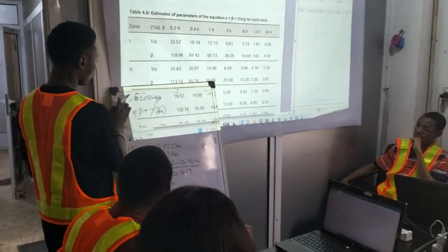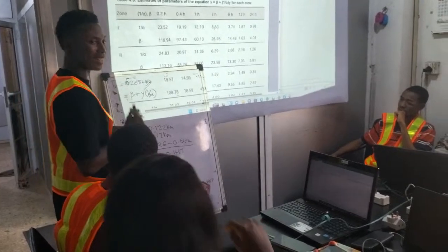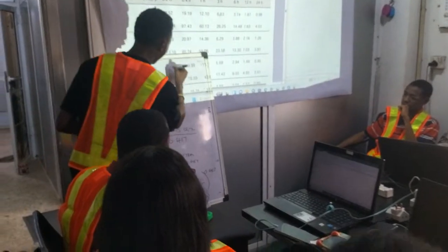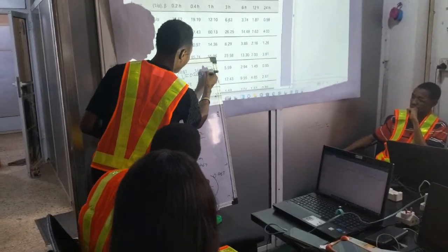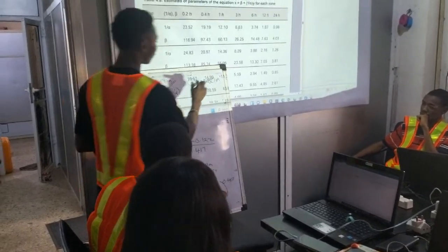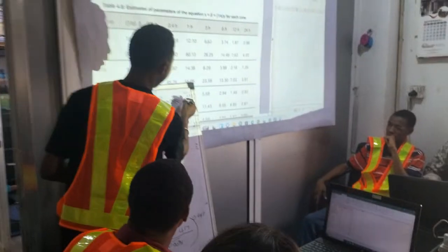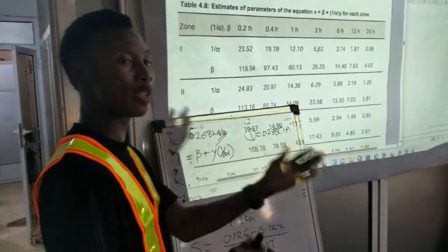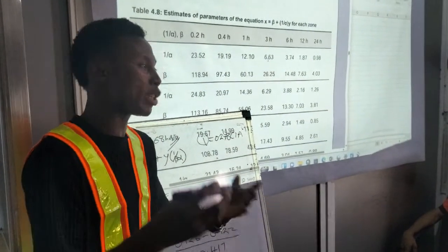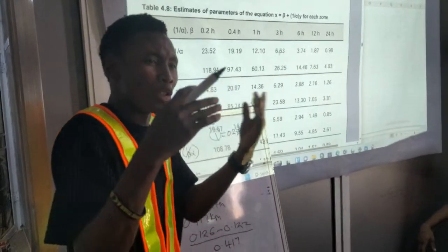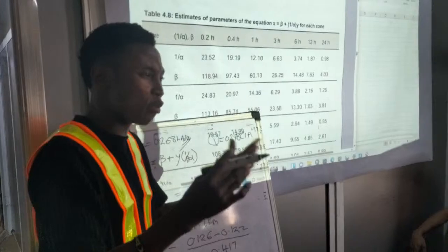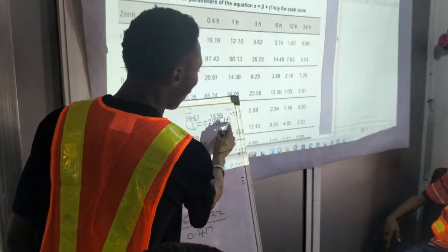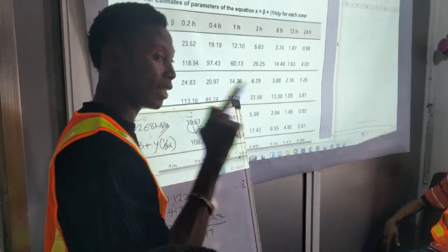This TC is what we're going to use to calculate for our what? Intensity. Remember our TC, time of concentration. Remember as well, our Q is what? 0.278 CIA. Our C is the coefficient of runoff. We'll calculate from that. Time to use human judgment. If you see the site, you check: the buildings here, are they industrial buildings? Are they private buildings? What is the land for? Take that into consideration before you calculate your C. Long story short, we got our C. Our area is the catchment I've shown you earlier. There is an area for that catchment.